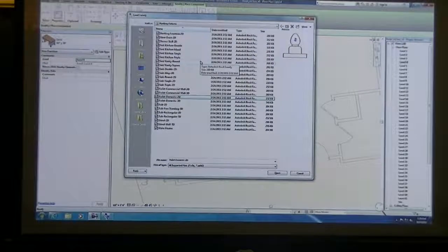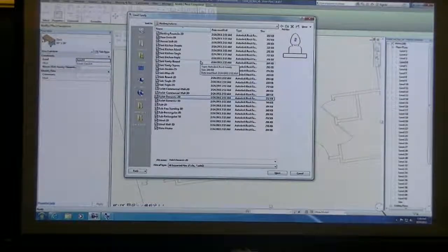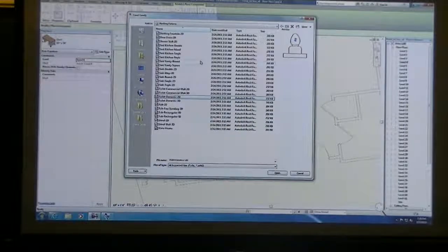as well as nowadays manufacturers, and this is where BIM and Revit is starting to come in handy, is that all manufacturers are now pretty much taking their products and putting them in Revit as a family component that you can download and then place into your model. So if you're working on, let's say, a residential house, and I know I'm going to be using Anderson Windows, I could go to their website, Anderson Windows, and they'll have a section for architects, and then they'll have a section where you can download Revit families, and then you can actually be placing the exact family model that has the same parameters that are associated with that manufacturer into your model.